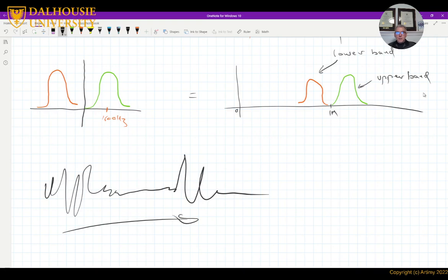And these are the ones that you see in the slides. Now these represent, when we shift them by modulation, they are duplicates. So it's like we are sending the same information, but occupying double the space in the frequency domain. So usually we eliminate one of them, right? When we send multiple voice channels, we don't need duplicates. So we eliminate one of them and keep only one, right?